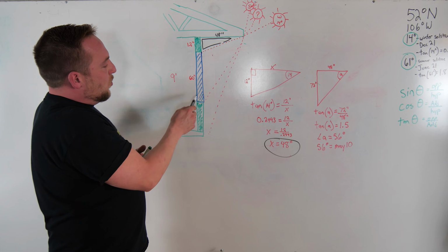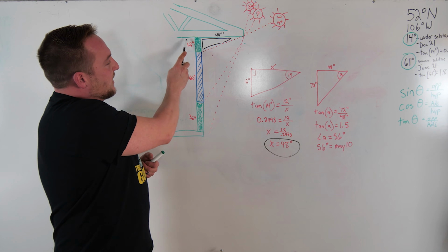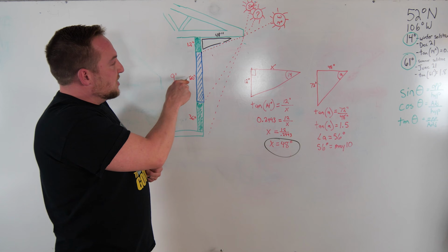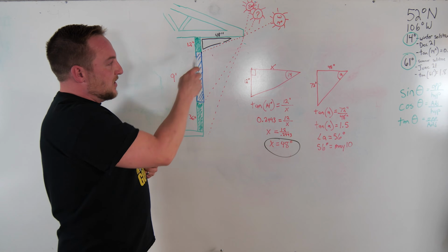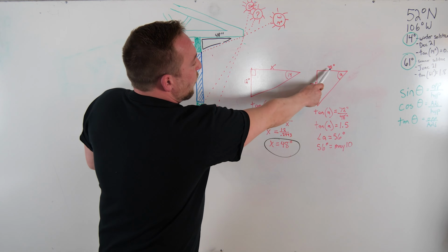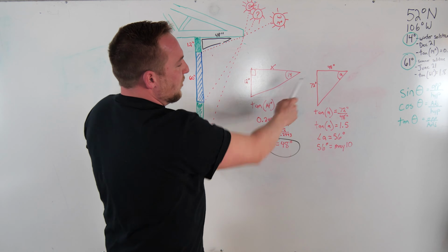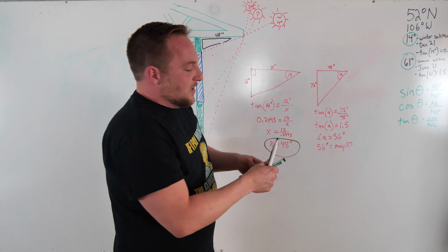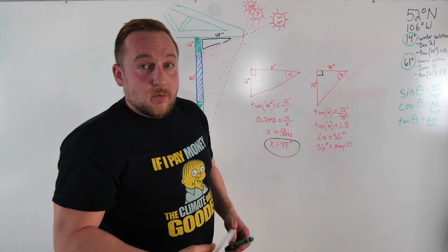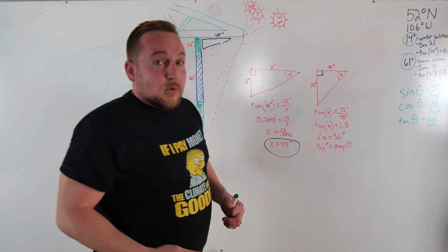So let's do a window that's 60 inches in a 9-foot wall. From the eave to the bottom of the window, we've got 72 inches: a 60-inch window plus a 12-inch overhang, 72 inches. So what we know now is a 48-inch overhang and 72 inches to the bottom of the window. This is a right angle triangle, and we don't have another angle. That's what we're trying to determine right now. So angle A is what we're after.